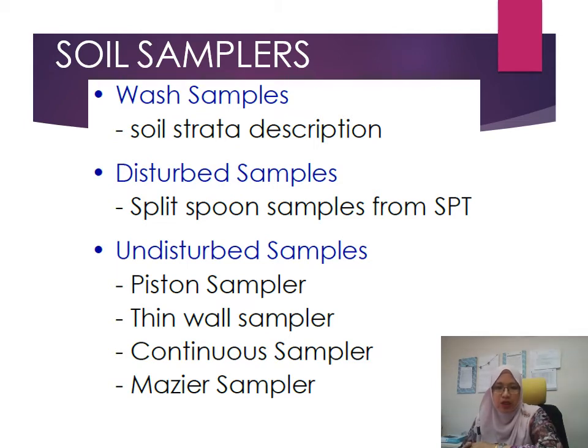What are wash samples? Wash samples can be obtained during the drilling operation. When we want to advance a borehole using drilling operation, we use drilling mud pumped into the borehole, and then all of the soil sample will be brought together to the surface by the drilling mud.